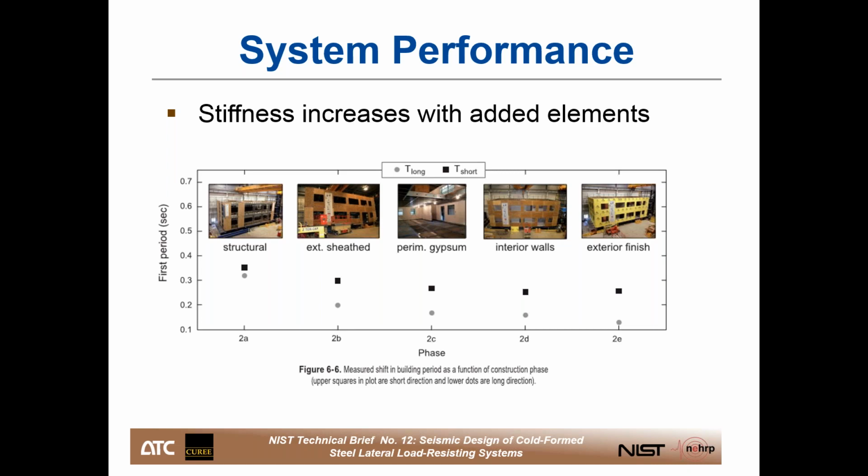But while our predictions were not at all realistic, the overall performance of the structure was quite good. So even the strongest shaking, which was actually, I believe it came up to either 1.1 or 1.2 of the maximum shaking that was experienced in the spectra that we used from Northridge, it only produced minor cosmetic damage in the sheathing around some of the openings.